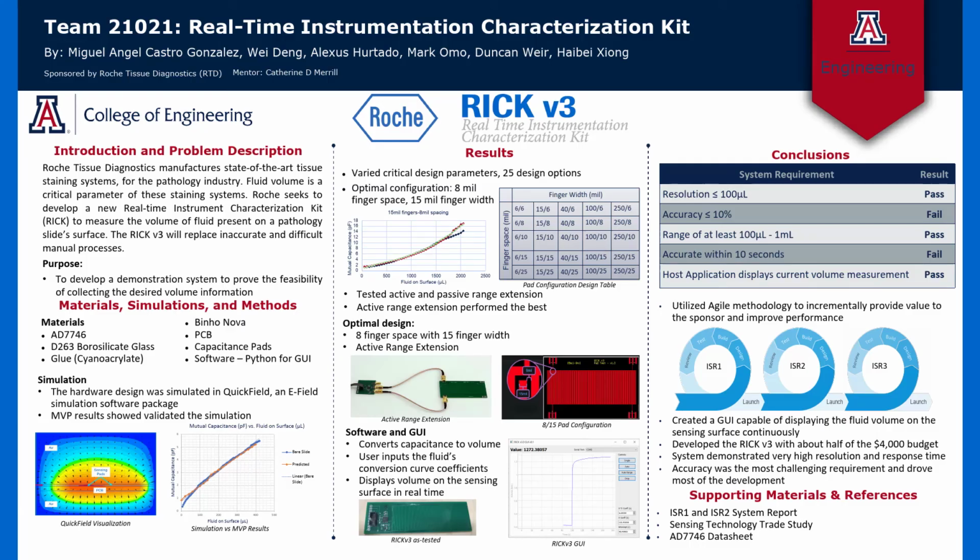Our system did not meet our requirements for accuracy. We believe this is primarily due to the mechanical variability in our system. Gluing down the glass was a hit-or-miss process, and this introduced significant variability, not just between runs, but between PCBs. Our team did not have the mechanical design expertise to address these challenges. The bulk of future work will be in driving down repeatability issues caused by inconsistent gluing, coverage, placement, and uniformity, with improved gluing processes and gluing jigs.